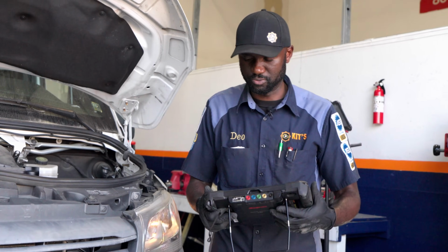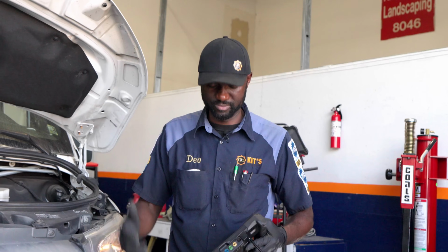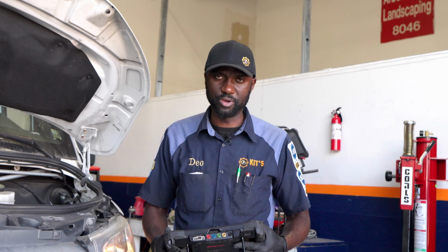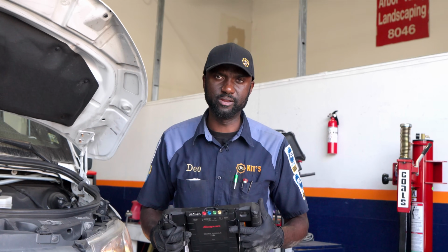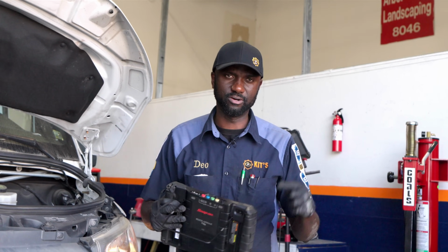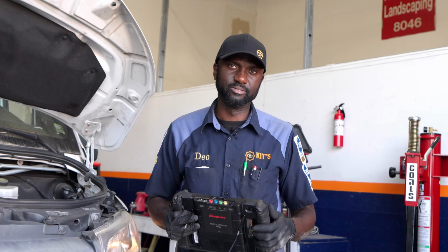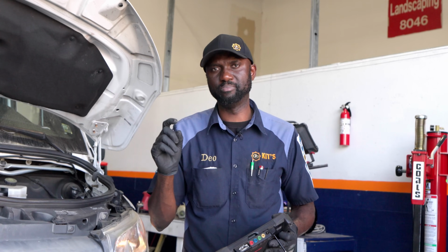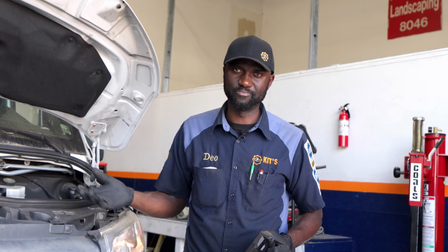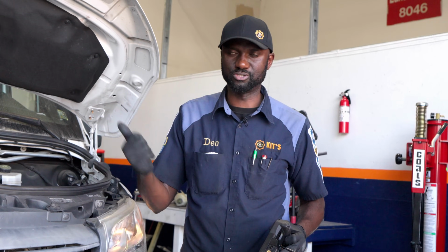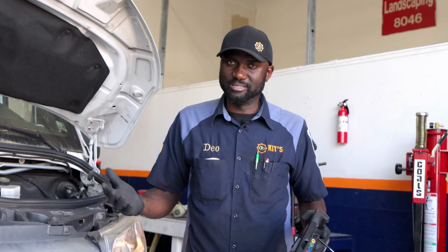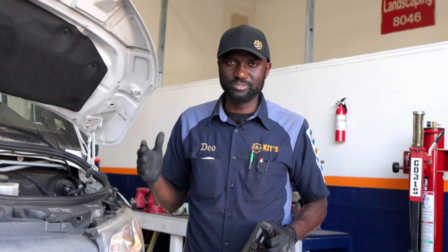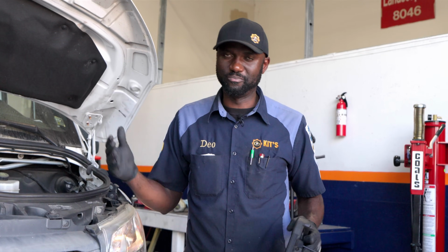So here's what I'm gonna do. We're going to lift up the vehicle, and then we're gonna remove the oil pan. Once we remove the oil pan, we're gonna get access to that solenoid on the oil pump. We're gonna check it out. We're also gonna check the harness. Usually it's the harness that goes bad, but if we're gonna go under there, we might as well replace the solenoid and the harness.